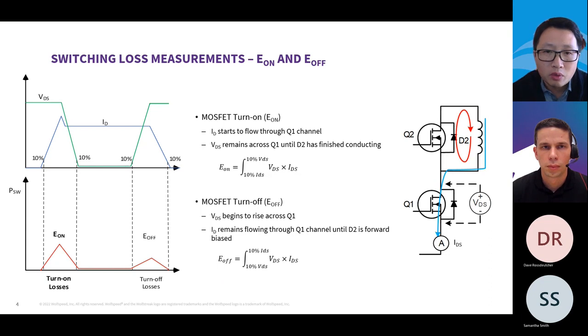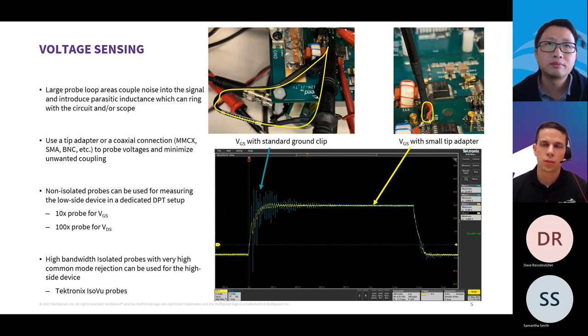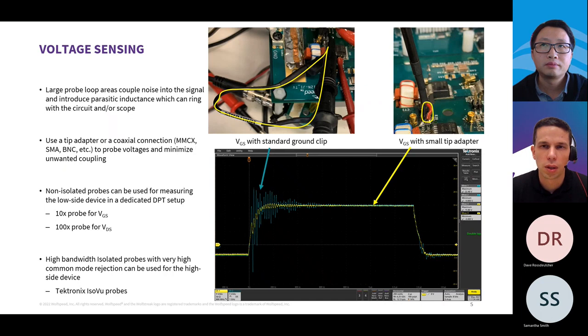So, Adam, one challenge I think is a particularly big challenge for silicon carbide is the high switching speed of such devices. When you perform a measurement in circuit, how do you accurately capture the current and the voltage given the consideration of such high switching speed and also the common mode noise? Absolutely, yeah. That's one of the fundamental benefits of silicon carbide, its quick switching times. That's what helps keep the switching energy very low. However, those fast dv/dts and di/dts make it challenging to make accurate measurements. So we've got some tips to help you be more successful at making these measurements.